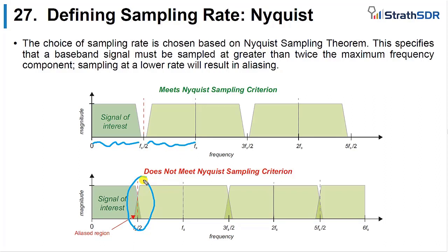We're just extending a little bit to start to think in the second order Nyquist zone, where our anti-alias filter is now a bandpass filter of some shape or form. And in these presentations, I'm talking about sampling at 4 GHz. Of course, in many systems, you will maybe choose not to go all the way to 4 GHz, and you may use some other frequency.